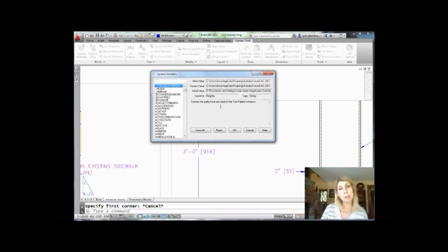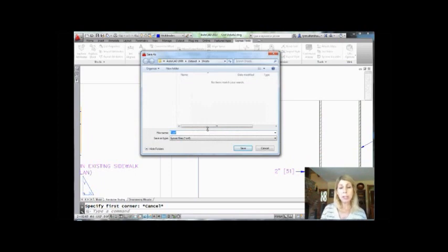All right, so what else does this cool command have to offer? Well, you will see down here that there's an option for save all. What is that? If you go in and you get all of your settings exactly the way you want them to be, your system variables, you might decide that you want to save like a little backup file that you can bring back in later on in case things go terribly wrong or someone comes in and changes your system variables around or whatever the situation is. And there are 2 file formats that you can save it under. An SVF file, which you could easily read right back in. I'll show that to you in just a bit. Or you could actually save it out as a script file, which is a pretty darn cool option. You could save it out to a script file and you could just run that script file as needed.